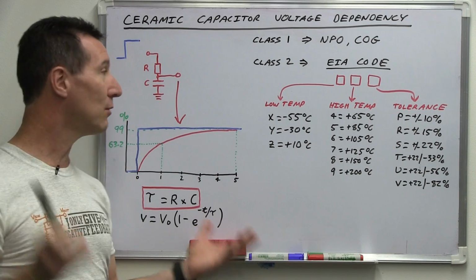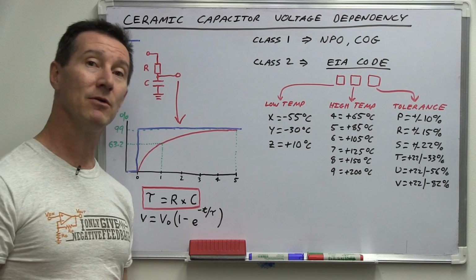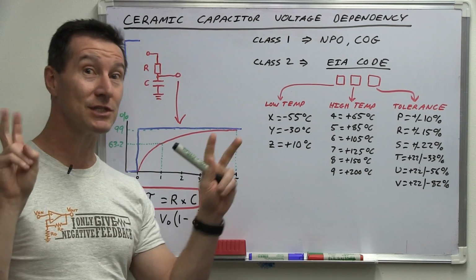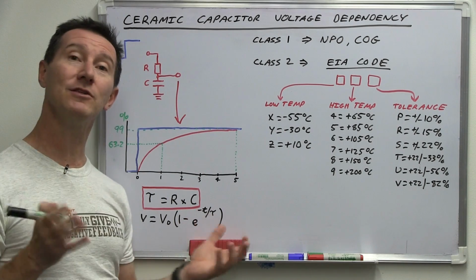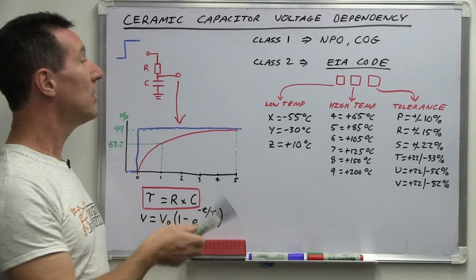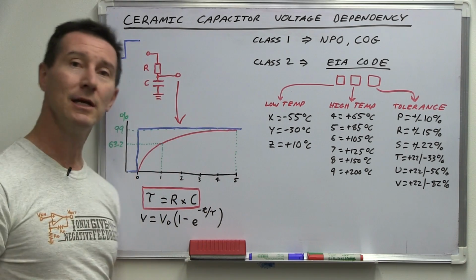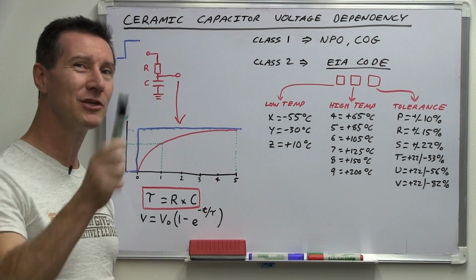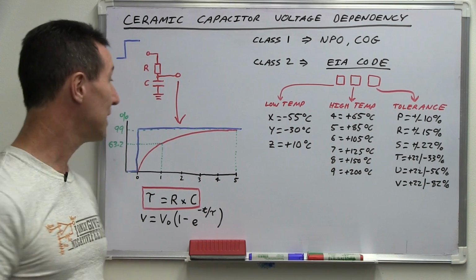Pretty basic stuff. Or an X5R, for example, is basically the same capacitor but with a slightly lower high temperature range. And you're familiar with these things, and as you might know, if you're an experienced designer, picking something like an X7R is a relatively stable high value capacitor to use, a relatively stable dielectric. So you might use, say, an X7R or an X5R in an RC time constant like this, but wait until we get to the bench. I'll show you a trap. It's not just about the tolerance here.